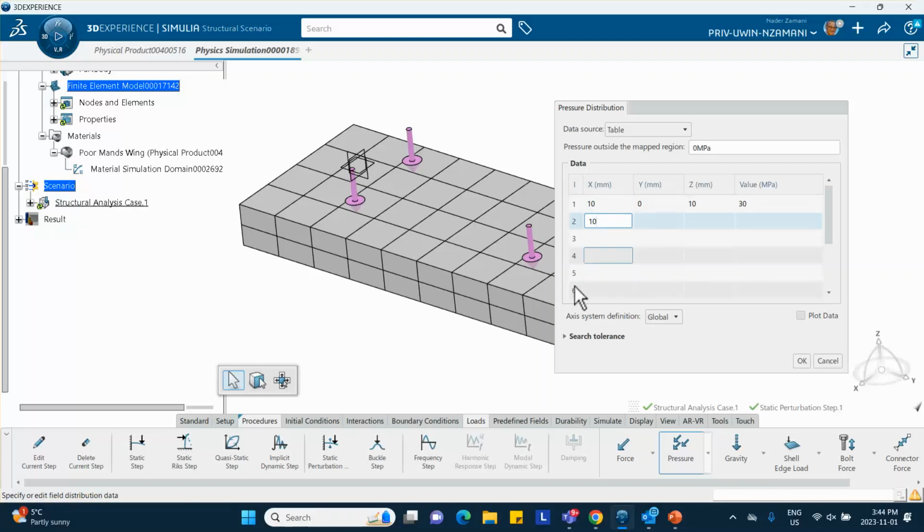These are your coordinates, the coordinates of the points where pressure is provided from whatever source. So 10, and Z is 10, and the value of the pressure is 20. It just happens that in this particular problem, they are the coordinates of these corner points, but they don't have to be. Whatever is in your Excel spreadsheet: 20 millimeters, height of 10 on the top face, and the value is 15.